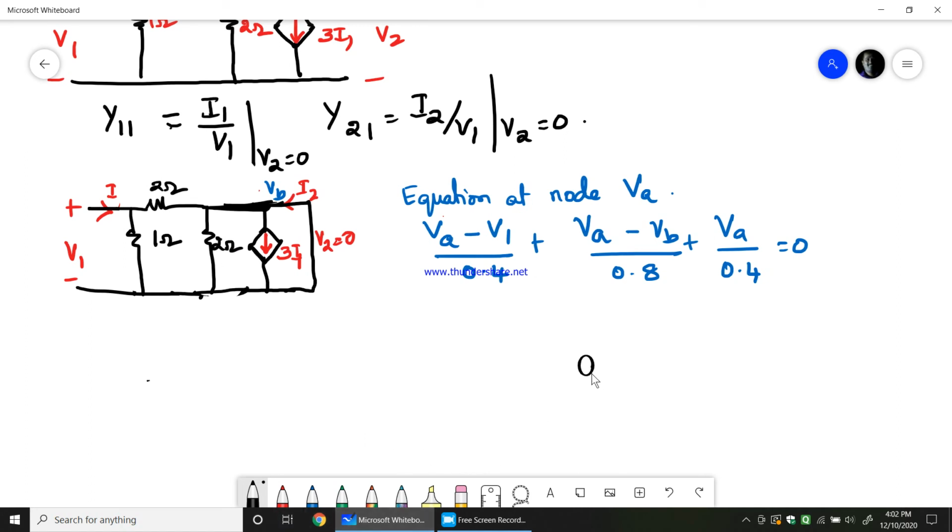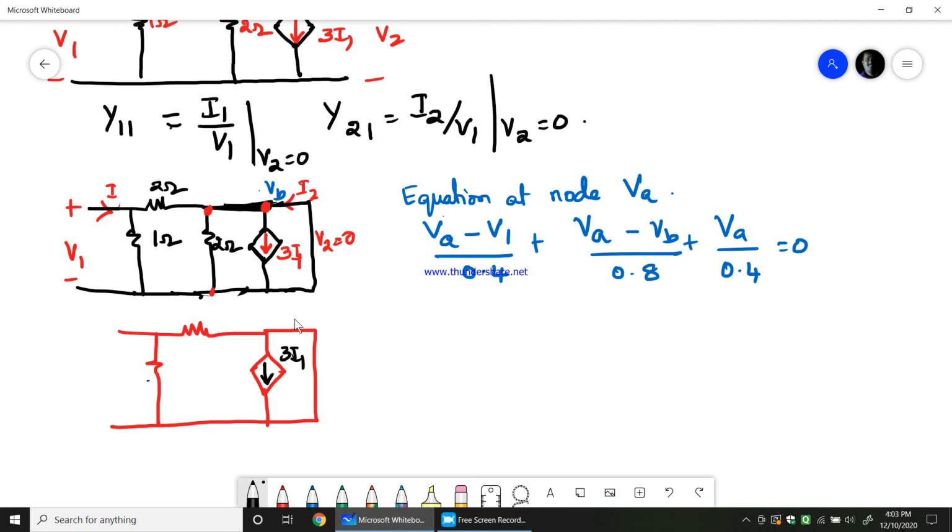So here, at this point, as we can see, the voltage is 0, so the voltage across this 2 ohms is also 0. So I can remove the 2 ohms and easily write another circuit like this. I can't remove the current source, because a current source cannot be zero here. If there is 0 voltage across a resistance, there is no voltage drop, therefore I can easily remove that resistance from the network. Now this would be the circuit that I get.